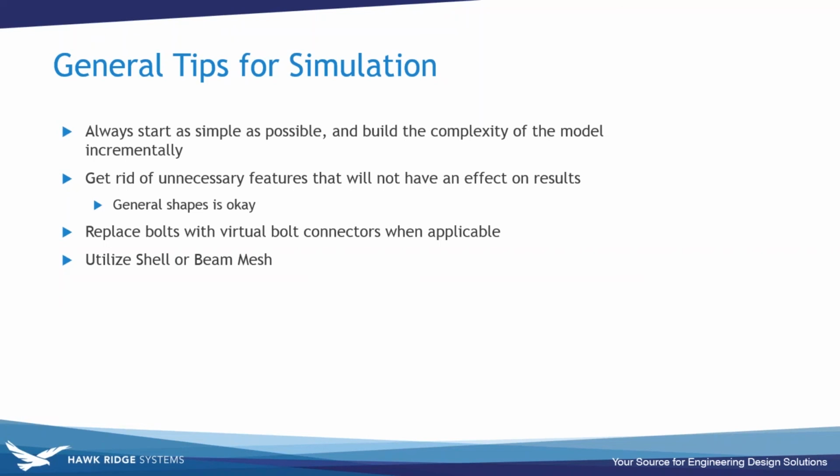If you still need to restrain them somehow due to how the fastener is going to work in real life, we have a lot of virtual techniques or virtual tools to replace those physical components. And then lastly, and I didn't really talk about this, not really the point in this webinar, but in the theme of simplifying your problem, maybe utilize shell or beam mesh.